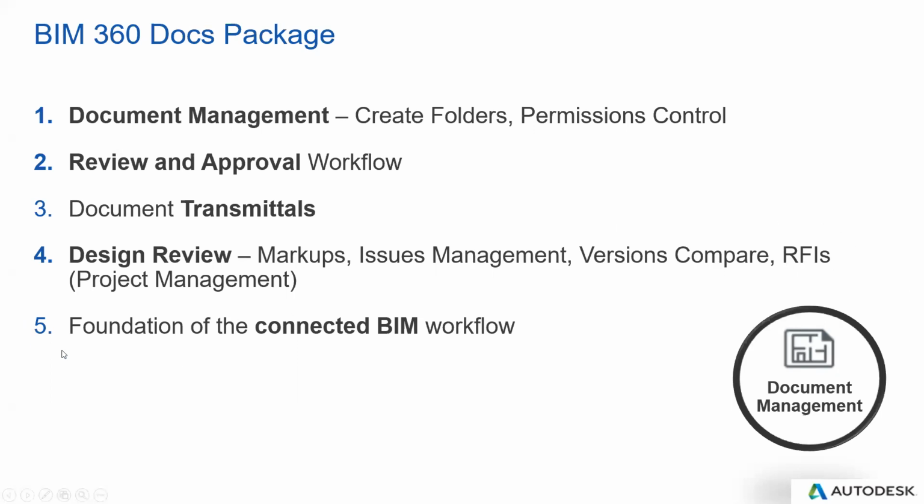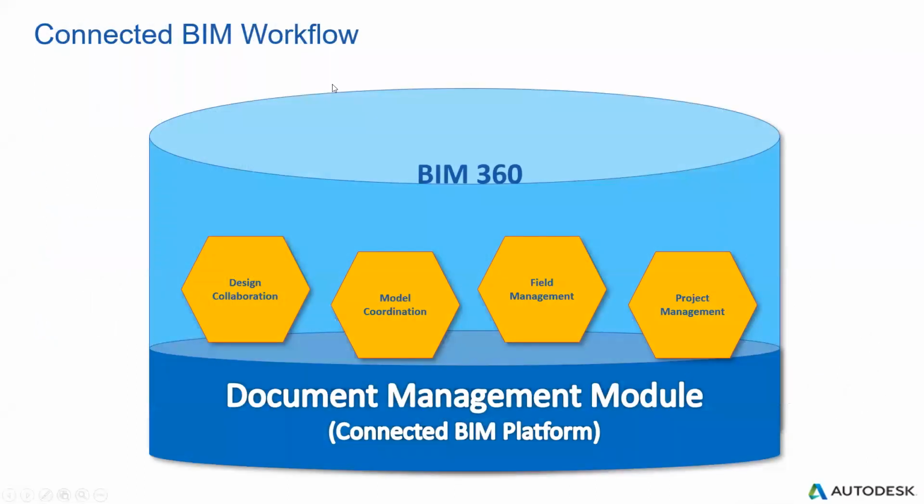And most importantly, it is the connected BIM workflow, which is the foundation of our connected BIM, the document management. You can see this diagram. It shows you a clear concept. So this is the BIM 360 site, and in the bottom is the document management module. All things should be stored in this platform. And then if you want to do design collaboration, Revit design collaboration, you have to put all the files here, and then we have the function here, or the clashes, model coordination, all based on the document management module.